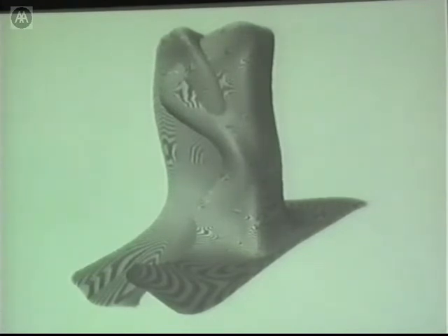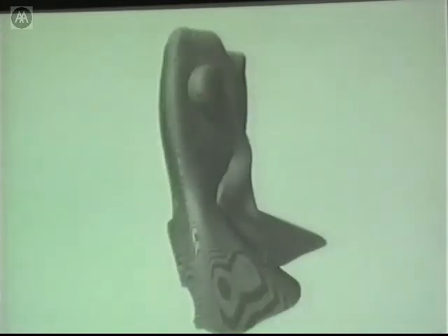Zebra analysis can highlight the type of surface continuity that might exist within such a surface, and I'm not going through detail here, but these surface continuities may have repercussions on how you wish to consider where seams in a structure might lie and how loads travel across curves with different curvature continuity. One problem with zebra surface analysis as a low-level type analysis is, of course, that once you change the angle of view, the stripe pattern changes, and so it becomes very difficult to analyze and discern what exactly is the pattern that needs to be considered and possibly fixed or strategized.